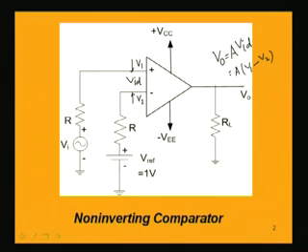So, the maximum voltage that is obtained practically is around plus 14 volt and minus 14 volt. These are the saturation voltages, a little below the supply voltages, that we practically obtain. So, the output voltage under no condition can go beyond 14 volt and below minus 14 volt typically. That point has to be remembered while studying the comparator.